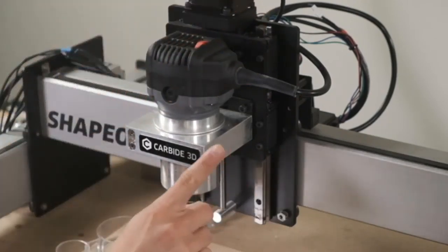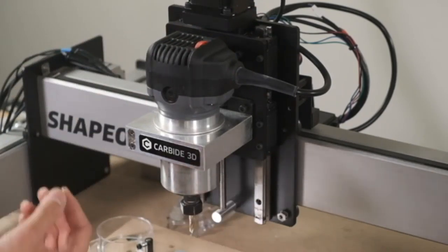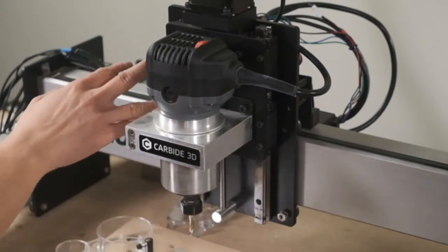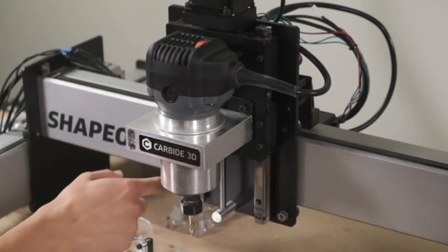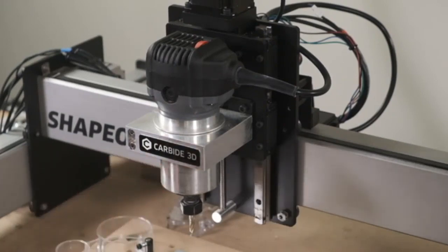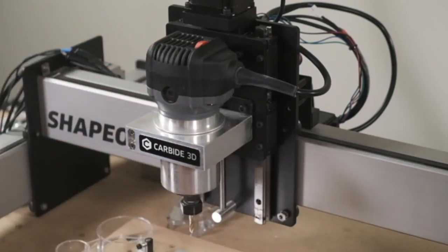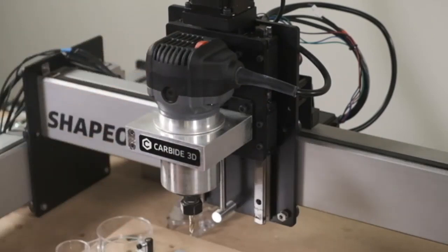But if you take a finger and you wipe the rail and it's not bone dry, there's still a little bit of lubricity to it, you should be okay. So for the most part, these are maintenance free, but if you're a super heavy user, within a year or two, you might get to the point where, hey, these rails are dry, and maybe the bearing blocks are a little squeaky. Hopefully it doesn't get to that point, but that would mean that you'd want to reload these with a little bit of grease.